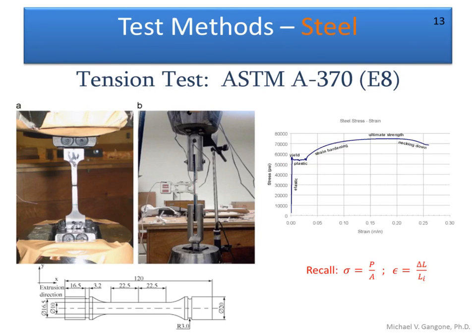All right, so the peak point right here is the ultimate strength of the material. We just come over here and determine that value of stress. This point here will give us our yield stress, and then this point will tell us what the failure load was and what the failure strain was. So how much strain the steel was able to take before it actually broke.